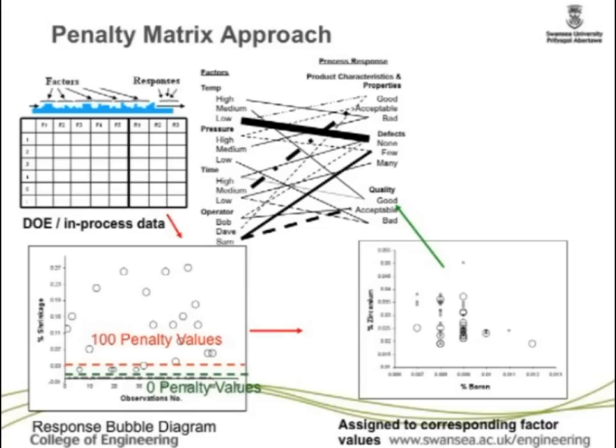Now these process responses can be conflicting. Shrinkage, optimized chemistry for reducing shrinkage is different to optimized chemistry for increasing tensile strength. They contradict each other. So how do you find the common platform which will say that, okay, I'm going to minimize shrinkage, but not at the cost of tensile strength? And that requires a quiet hour of analysis of these reports and this variation. But it's possible, and we'll see that in the presentation in the afternoon.